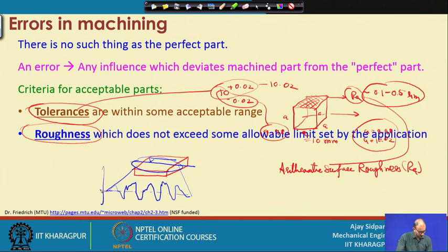This will be 0 and here it will be 10 micron or whichever way it is moving, that means your magnitude or amplitude is moving up and down, and that will be considered as the scale or range on which this particular roughness varies. But you will never get this profile as a straight line, correct, because it is of stochastic nature.